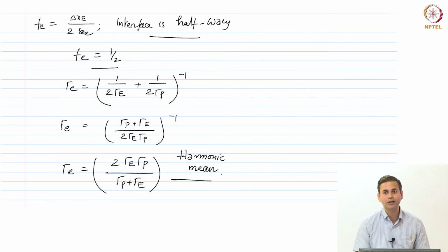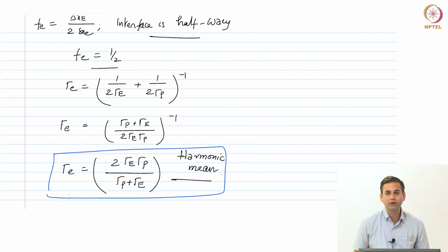And then we said if you model the heat flux instead of calculating gamma by some ad hoc method, it gives you a better result. That's all we have claimed, but we have not proved anything. We just found another expression for gamma little east, which is the harmonic mean of the two thermal conductivities that we have rather than the arithmetic mean of the thermal conductivities. So what we do next is we consider specific cases and see whether each of these things works or not.